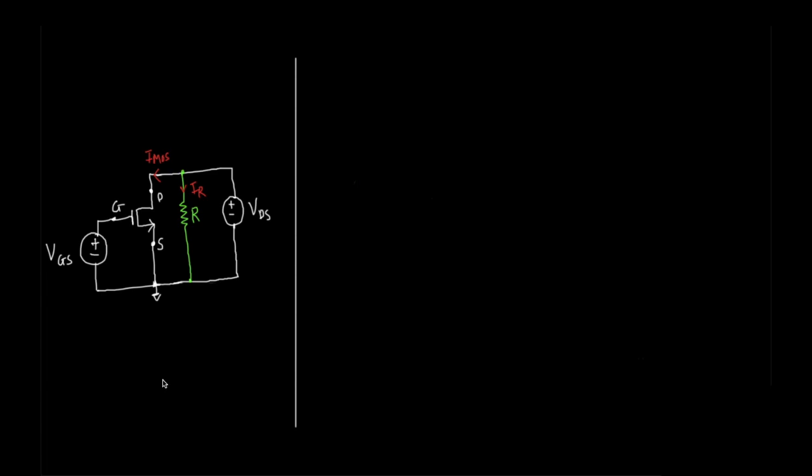This is the first circuit we saw when we started this video. What you see here is a circuit with forced VDS voltage. We know that we should put R across R out in the small signal model to get control over the gain. But if we put a resistor across VDS here, there will be no effect on the circuit. This is because the current through the MOS is not getting altered by the addition of R. So this will not work.